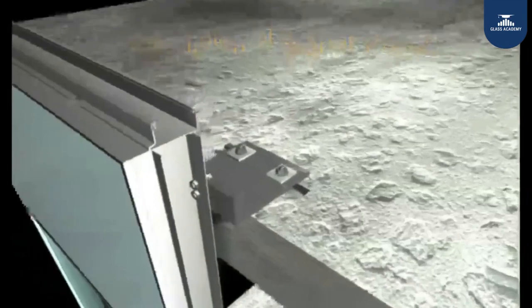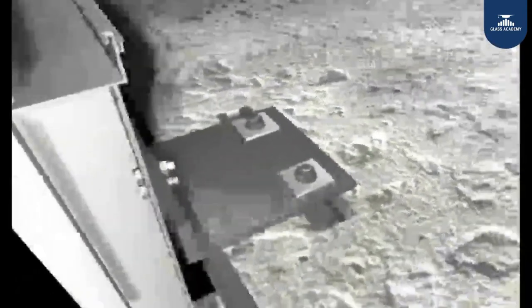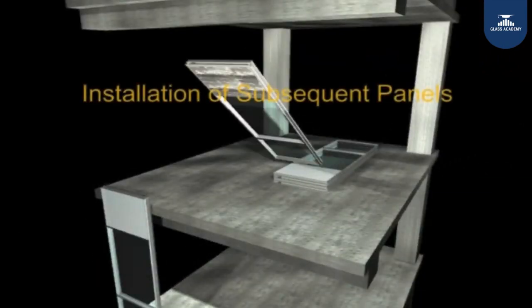Now imagine this panel that you see here has 3 glasses plus spandrel. In all the other systems, you install all these at site. What you see here is, okay, you have 1 glass, 2 glass, spandrel. The unit system you do in the factory, you bring them all together and you put it up. But with the other systems we saw before, you just do the grid, you put in all the mullion and transom, then you do the glass piece by piece at site.